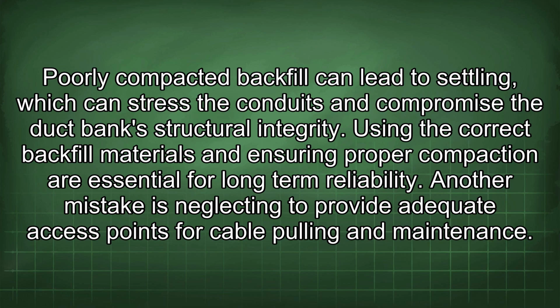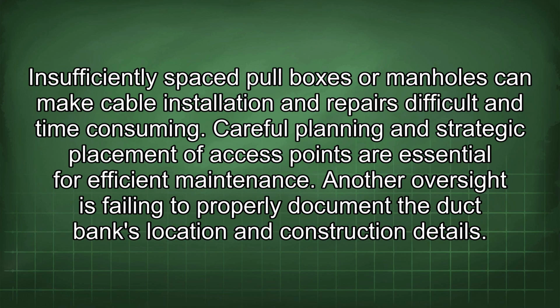Another mistake is neglecting to provide adequate access points for cable pulling and maintenance. Insufficiently spaced pull boxes or manholes can make cable installation and repairs difficult and time-consuming. Careful planning and strategic placement of access points are essential for efficient maintenance.